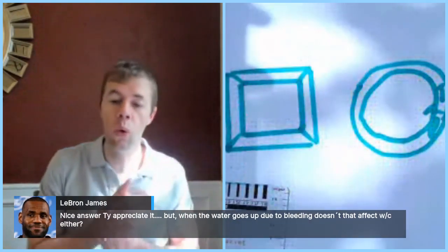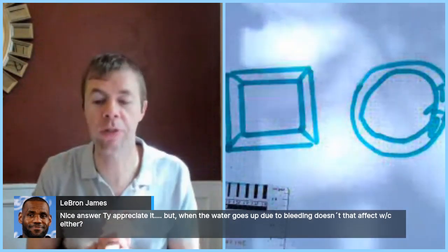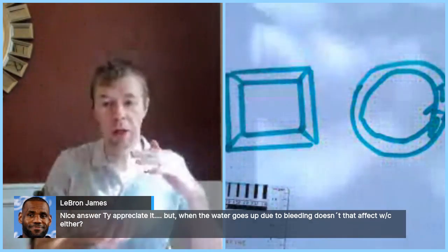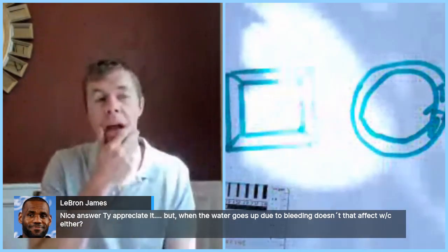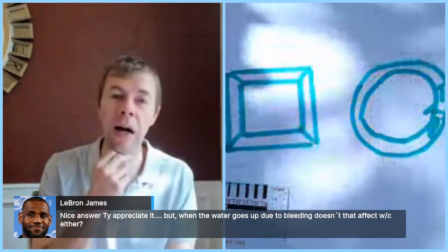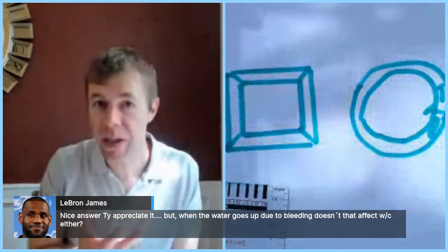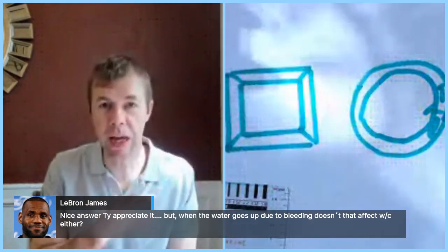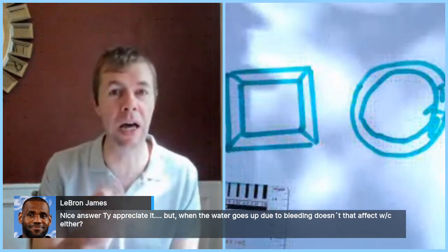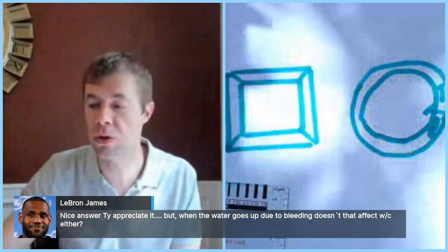Okay. So when water goes up due to bleeding, doesn't it affect the water cement ratio? Sure it does. Bleeding is when water comes out of the concrete, and it will reduce the water cement ratio of that concrete, but not by a lot. And if your concrete's bleeding a whole lot, there may be something else wrong. You may have a poor mix design. It shouldn't bleed a ton in modern concrete mixtures. But if the bleed comes out, it's no big deal. It reduces the water cement ratio.